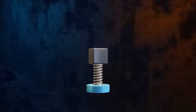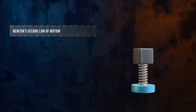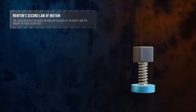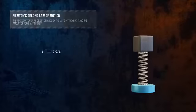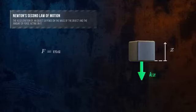The way the system vibrates is defined by its equation of motion, which can be determined by applying Newton's second law. The second law states that the sum of the forces acting on the point mass is equal to the product of its mass and its acceleration, F equals ma. We can figure out the sum of the forces acting on the mass by drawing a free body diagram. There is only one force, the force exerted by the spring, which is equal to the displacement x multiplied by the spring's stiffness, k. And so, we obtain the equation of motion for the system.